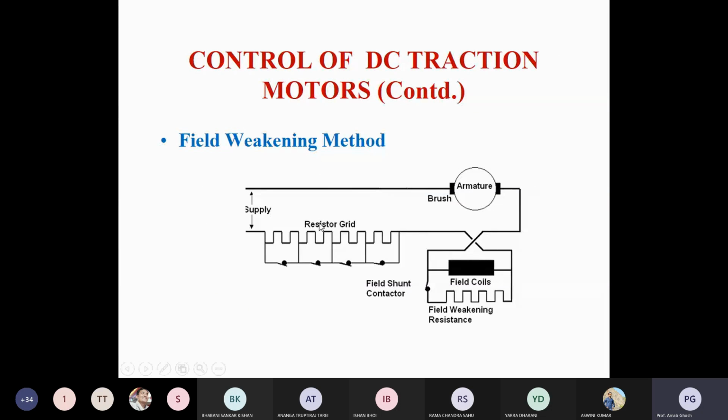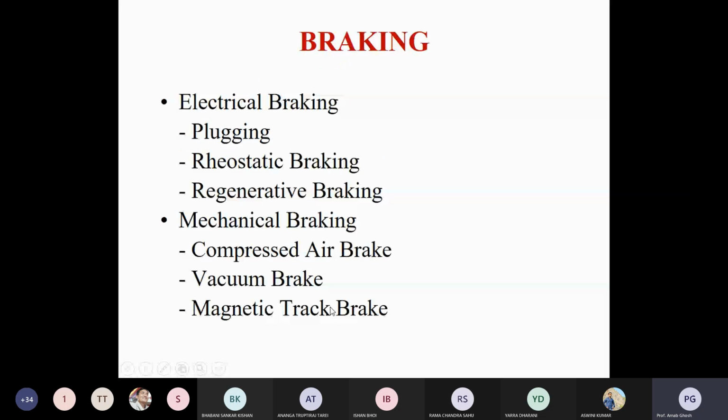So as per the speed control of your motor, you can go for connecting the breakers one by one. The switches are there, so one by one you can turn them on to divert the additional resistance path. So you can go for rheostatic braking, also known as dynamic braking. The additional energy will be dissipated in the form of heat. So rheostatic braking is also very energy consuming.